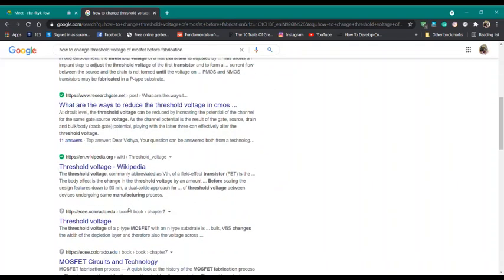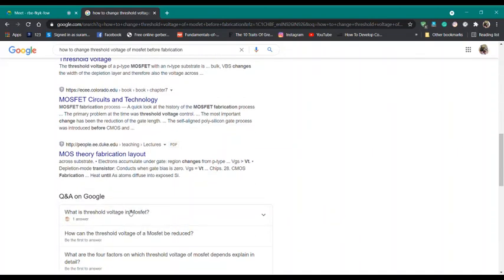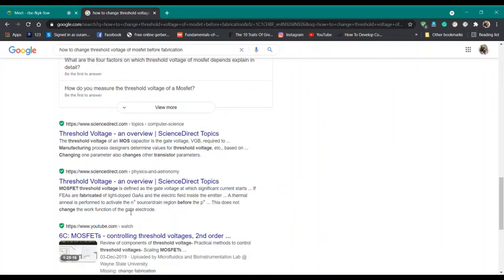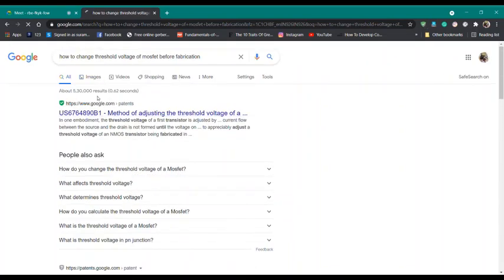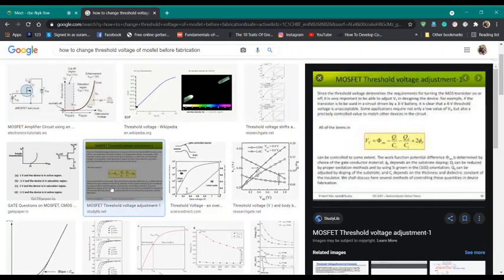Yes, sir. One thing is body effect, sir, and another one is channel length modulation, sir. Channel length modulation I mean, change the threshold voltage. Sir, I mean like dimensions of length and the width. TOX also, sir, like thickness of the metal oxide. Channel length is not the right answer. So what is the right answer? What is the basic definition? What all parameters define your VT?